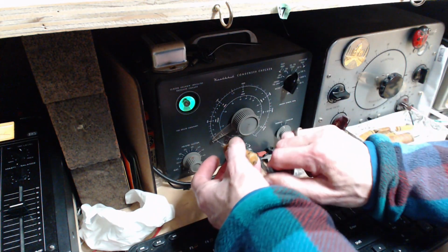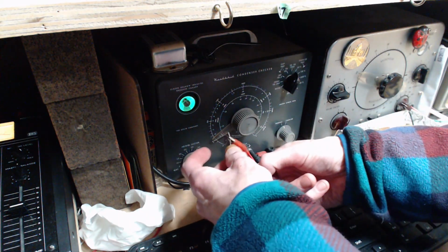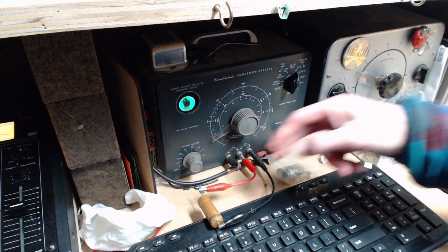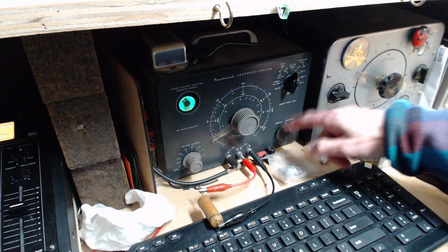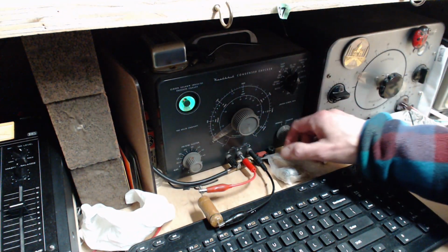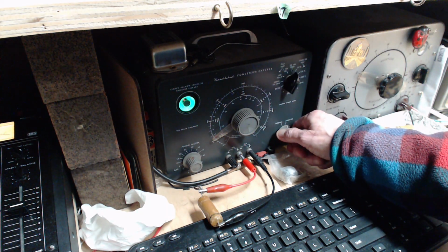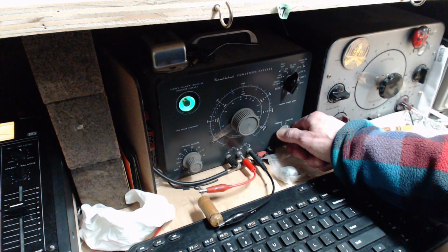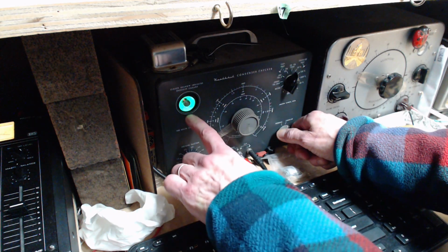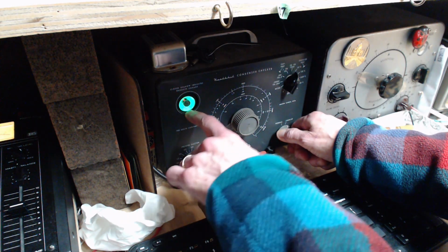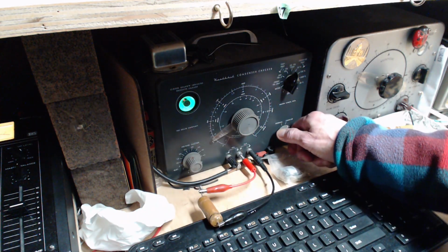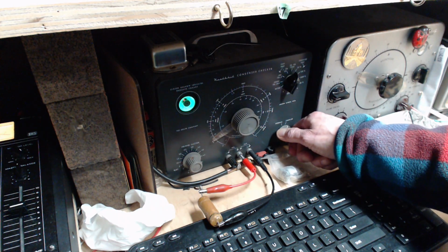Okay, we're going to hook up the capacitor. We already know this guy is leaking enough to show up on those test results. Big capacitor, 50 volts. What do you say? You give it some time now because it takes time to charge. So the eye is just on the verge of opening a bit here. Very leaky capacitor. That's what this would amount to.